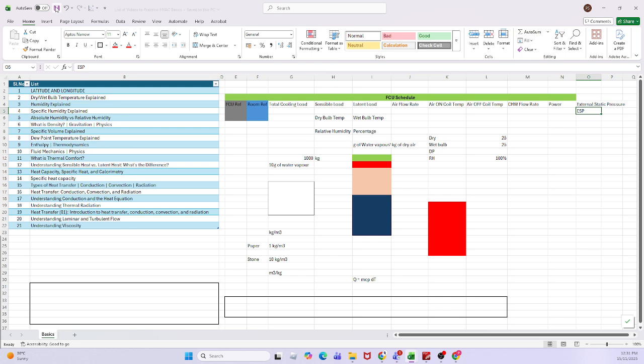Sometimes in the beginning you schedule the FCU and always keep it at 50 Pascal and the AHU at 200 or 500. How do they get that? We will do the pressure drop calculation based on ASHRAE. I will explain to you how to do that.